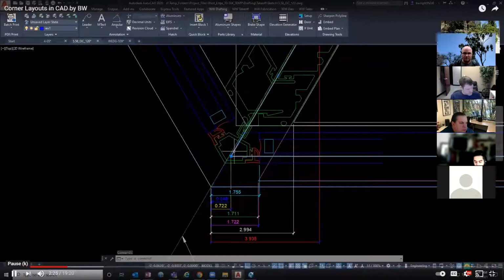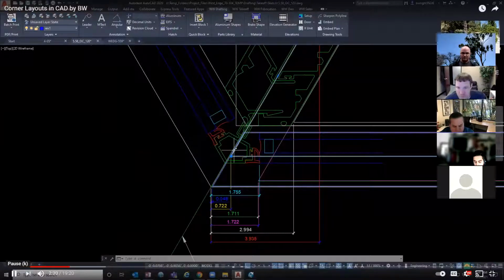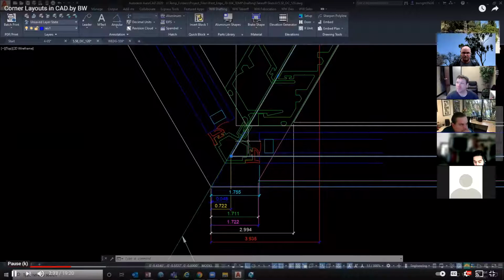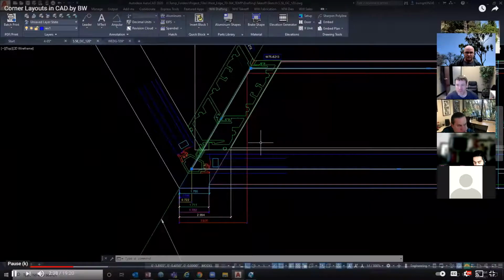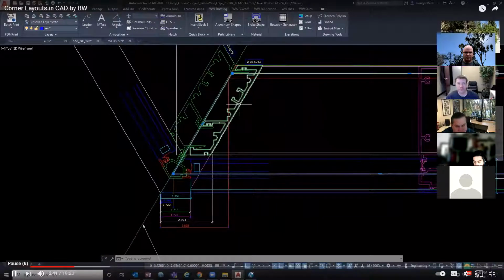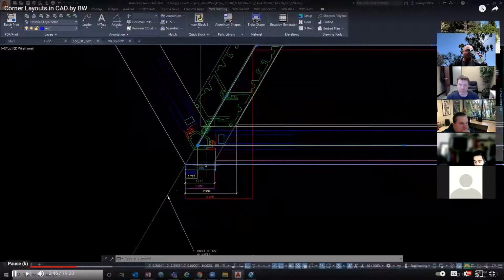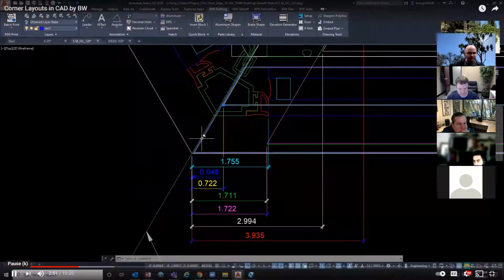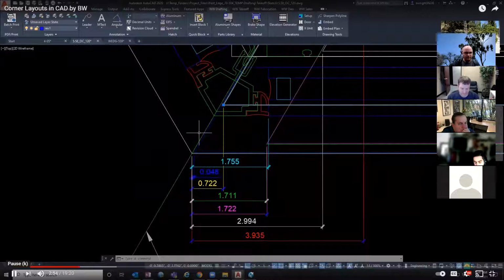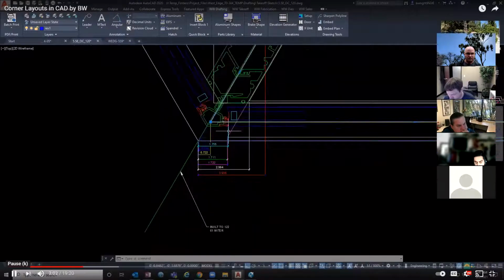So for example, the yellow sill track is tracking to here. This has an offset of 1/16 off the center line, and that creates a 1/8 gap between the mitered sill tracks. That's what our decision was when we looked at how the parts and pieces went together, so the field could install the tracks and do a proper seal in between them. The face stops in this condition are offset 1/32 off the center line, creating a 1/16 gap between the two. Again, for a similar reason, so that when the units are installed, there's some installation and thermal tolerance.